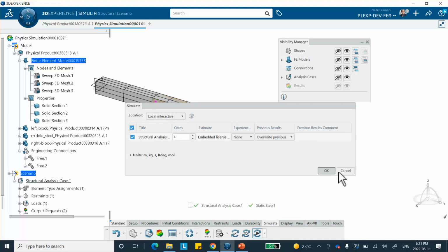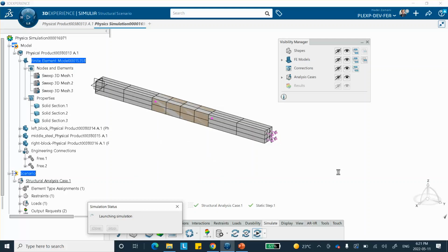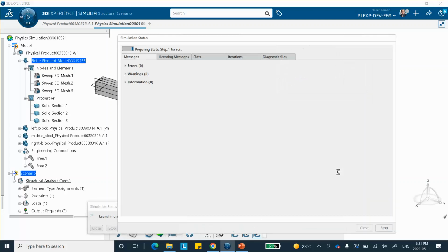Remember, we're doing a linear analysis, so it's very fast, and I did it in one shot by saying that minimum time is 1, minimum increment is 1, and maximum increment is also 1. So we'll do it in one shot. I also deactivated the area jump radio button because that's really not the purpose of this tutorial.